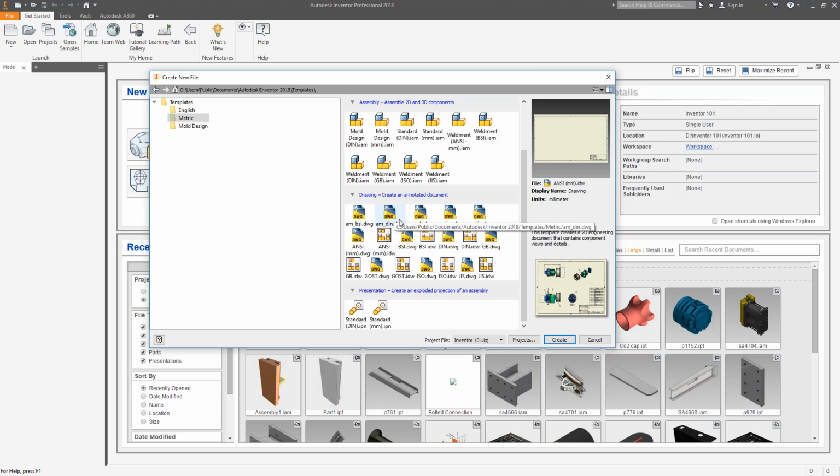So the cool thing about Inventor is you can create native DWG files if you want to, if you know you're going to be sharing your designs with other folks running AutoCAD, perhaps, vendors, other individuals inside your organization. You can very easily, just from the beginning, make a DWG as the standard drawing format. IDW is, I'm not going to say proprietary, but it's the default file format in Inventor for creating 2D documentation. So just be aware of the differences.